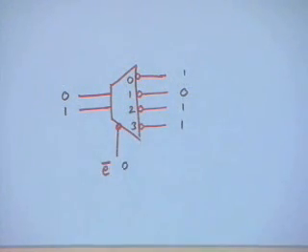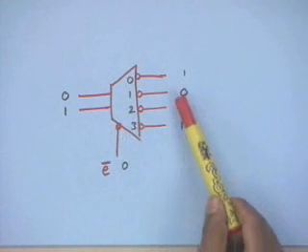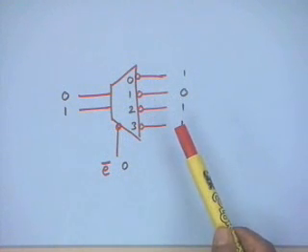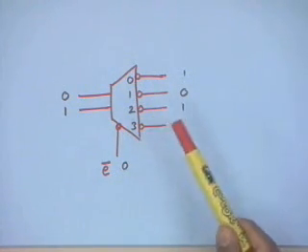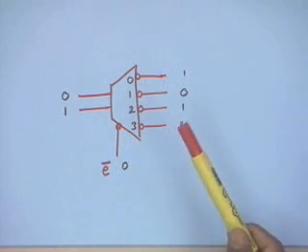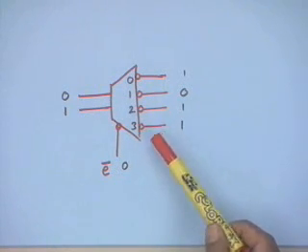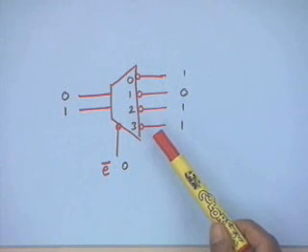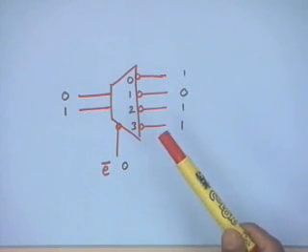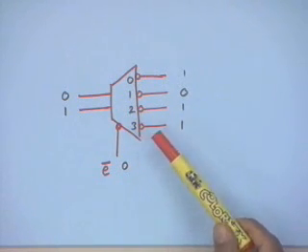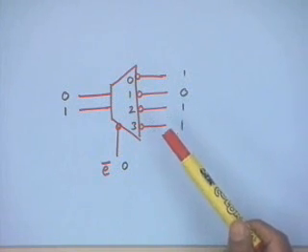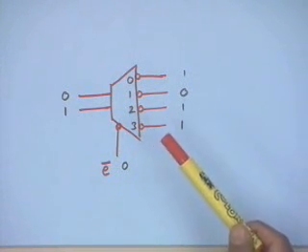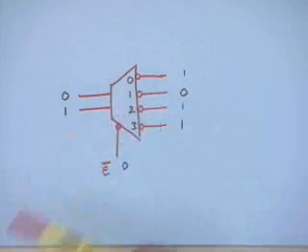Typically you get decoders as active low, both the enable input as well as the outputs. The reason being that within a ROM or a RAM, many of the times the decoders are used later, as we will see, for what's called chip selecting these devices. So it's simpler to implement an active low logic as an enabling input. So it is cheaper, and that is the reason many times decoders are found with active low outputs.